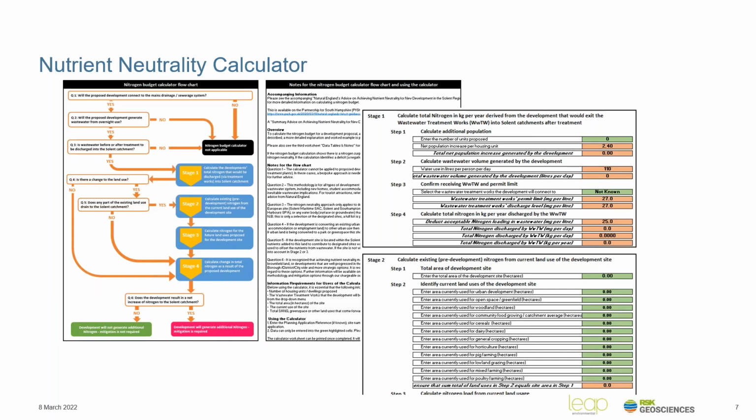For instance, you could argue that a retirement village or sheltered accommodation would have a different number compared to that value. You also take in things about how much water usage there is. So we're assuming there's 110 litres per day per person. That might be correct, but obviously the more water you're using, the more water you've got to treat. And then there are parameters around the design configuration of the actual wastewater treatment works and the performance of it.